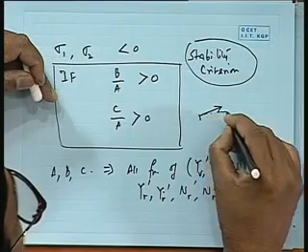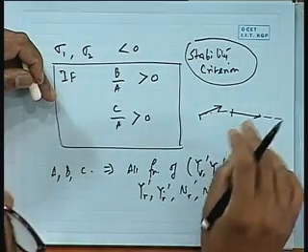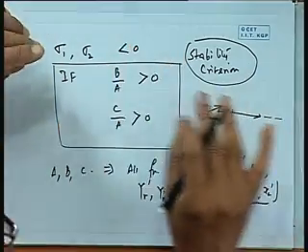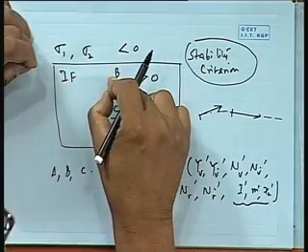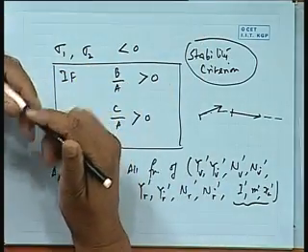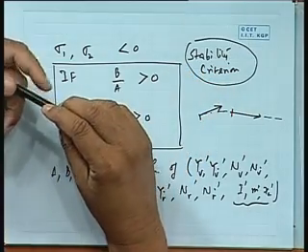See, the ship was going in this direction. Now, you have got a disturbance. So, it actually eventually comes back and begins to go on a straight line. When it goes on a straight line, you have got v dash 0, r dash 0. So, it simply ensures that the ship finally goes on another straight line only. That is important, because it is not positional stability, directional stability, but straight line stability only.